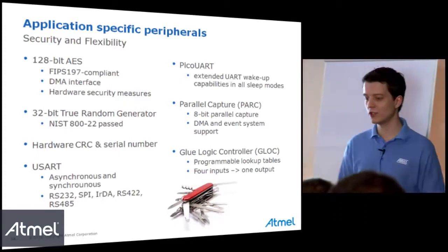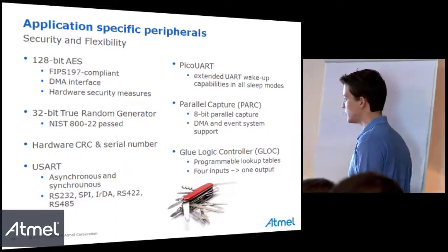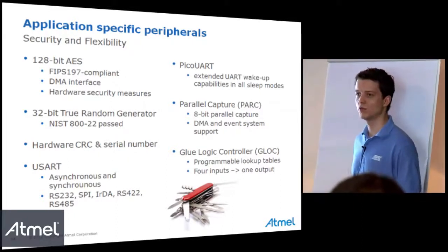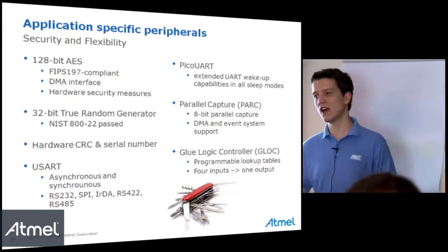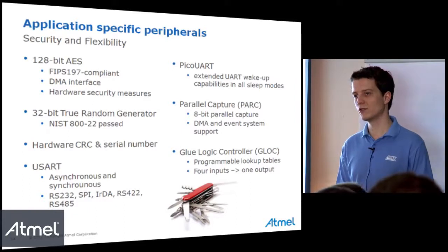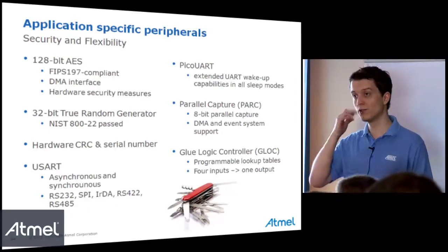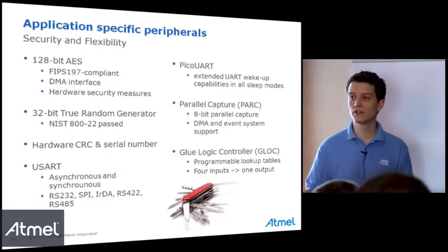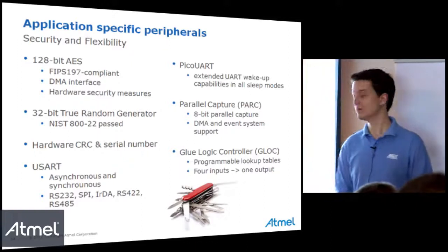And a glue logic controller. The glue logic is a programmable lookup table with 4 inputs and 1 output on the device. It mainly allows you to avoid the usage of external components for basic operations such as OR, AND, or XOR, for example.